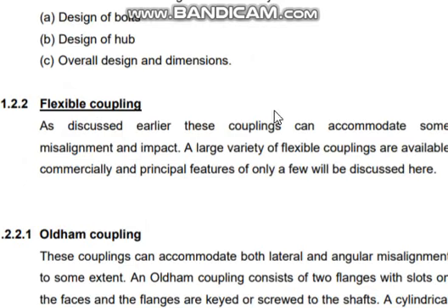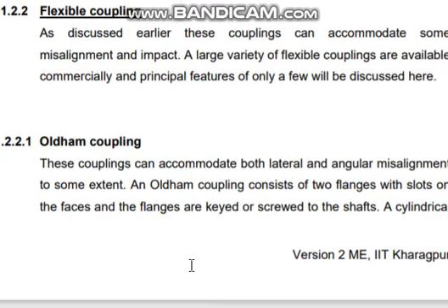Okay, next, flexible couplings. In these, as discussed earlier, flexible couplings can accommodate some misalignment and also some impact. They will isolate the shocks and vibrations. A large variety of flexible couplings are available commercially. The principal features of only a few will be discussed here. Oldham coupling.